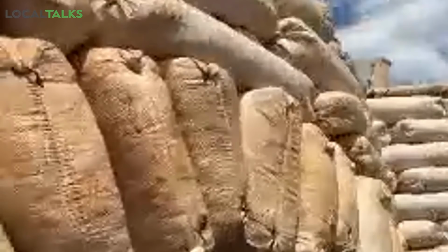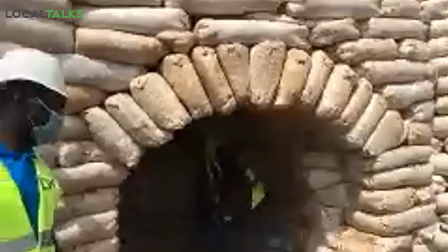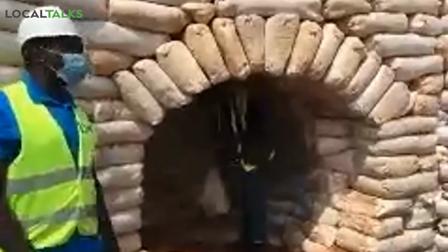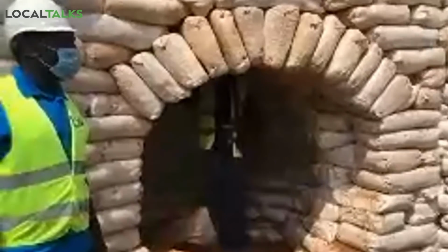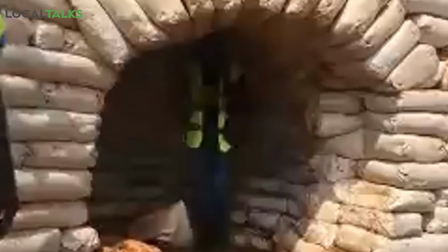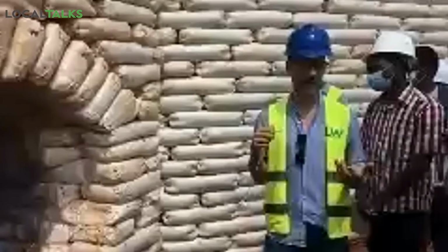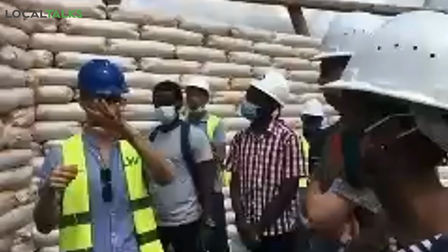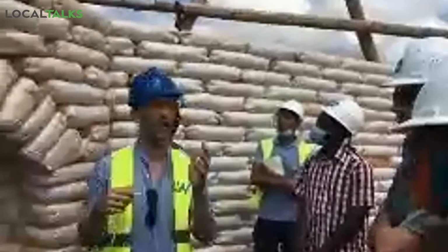The experiments we have made so far, the question is whether it will be sturdy enough. The experiences we have made so far with the lime earth plaster samples is that they are immensely hard, strong. What we will not do is sharp corners for that reason, because that is always what breaks out. But this also works extremely well with this very smooth language that we are doing here. So we will curve everything.